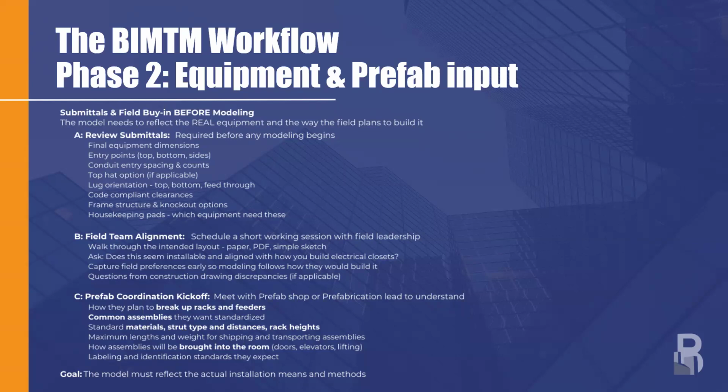We want our modeling to reflect the real submittals, the real gear, the real field intent, and how we can utilize it for real prefabrication. Now, and I'm going to say this with a gigantic asterisk, if you need to model for coordination reasons before we have some or a lot of these answers, you can do a generic zone that encompasses your worst case scenario.